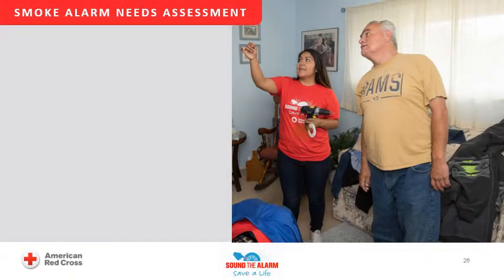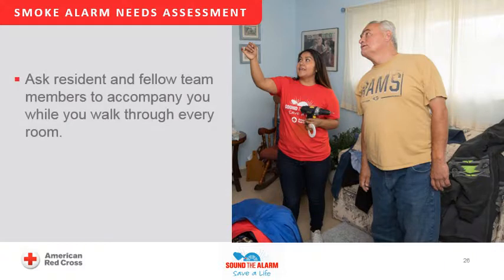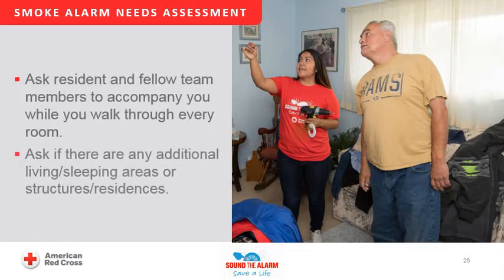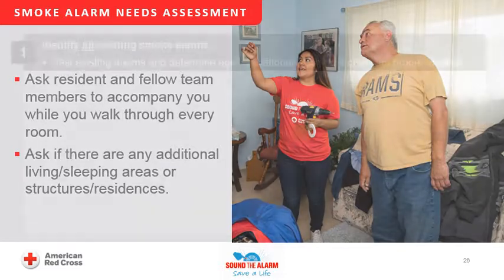Conducting a smoke alarm needs assessment during the in-home visit has been identified as a best practice technique to ensure that the smoke alarm installer understands the unique needs of the resident and household before installing any new smoke alarms. These 4 steps represent the critical components of a smoke alarm needs assessment. Ask the resident and fellow team members to accompany you while you walk through every room. Ask the resident if there are any additional living or sleeping areas, or structures or residences on the property.